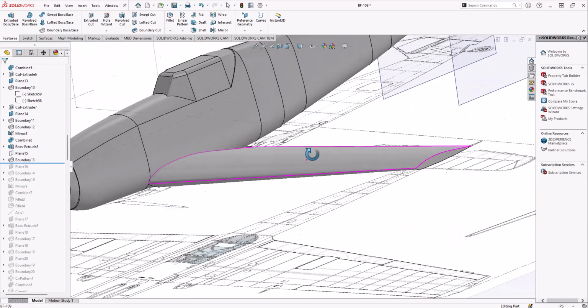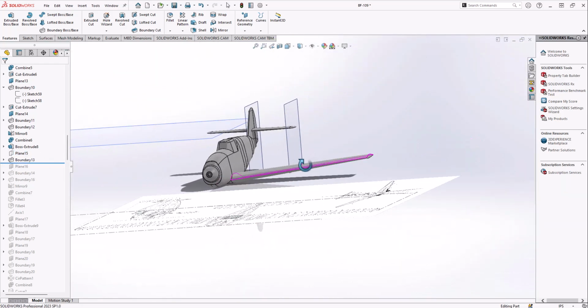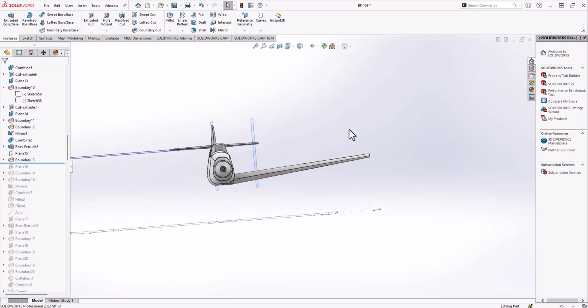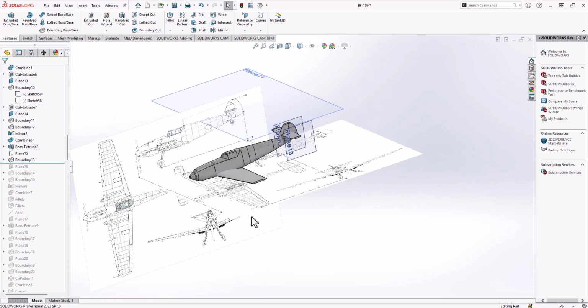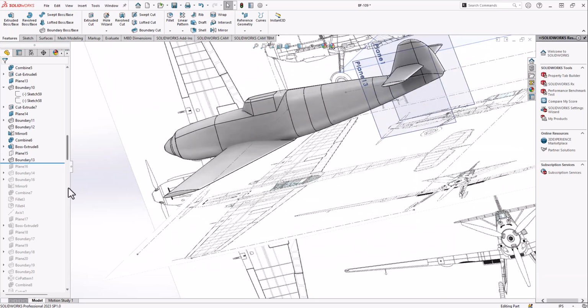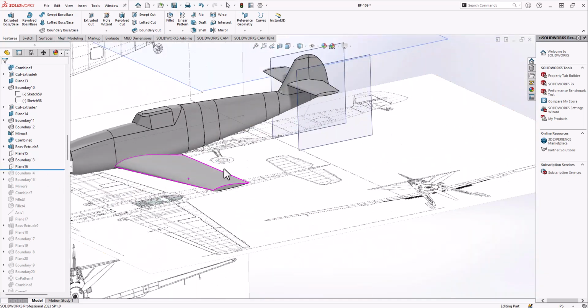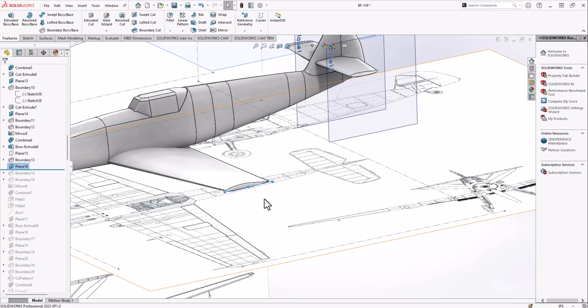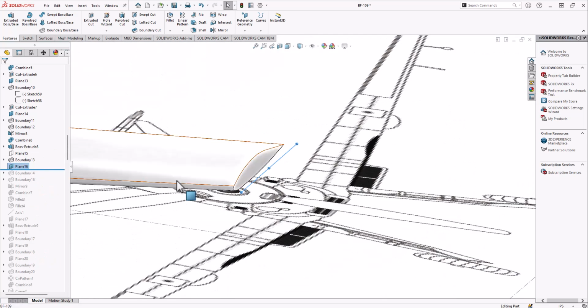This time, the wing does have that upward camber. That's not the right word, upward slope. So I have that captured. And then I do the same thing I did earlier with the plane at the tip to round off the tips of the wing. So I'll hide that again, and that's just these steps.